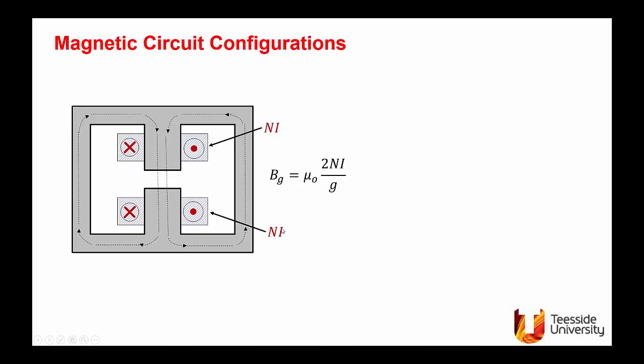Now we are going to start with some magnetic circuits with air gap, leading to the typical magnetic circuits used in electric machines. So I have a large air gap here and two salient parts. Each part carries N turns carrying current I. If you apply the right-hand rule, you will find that the flux is going down here and going there.